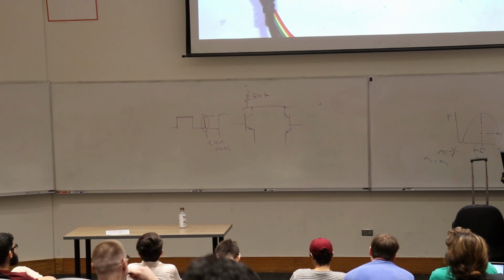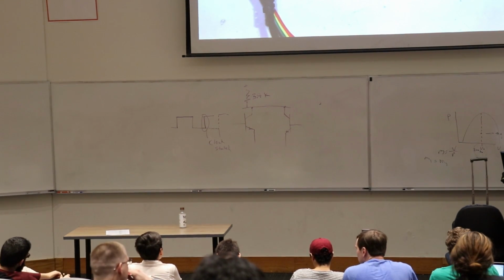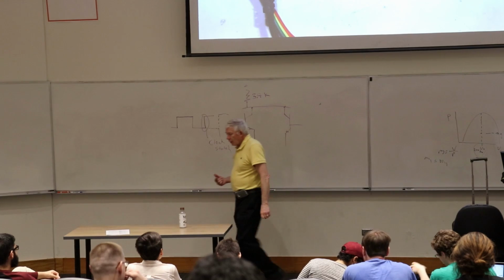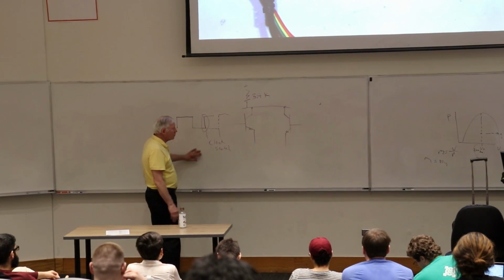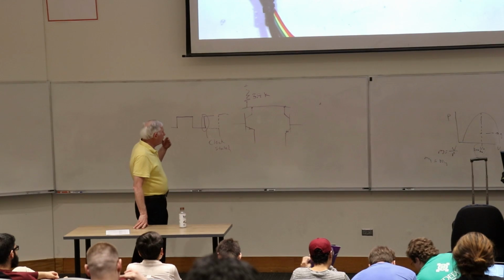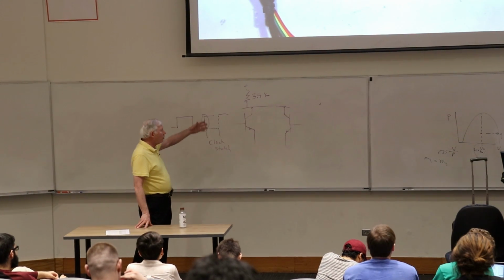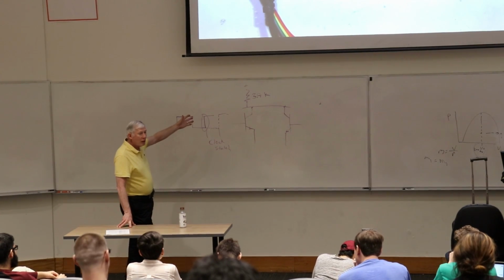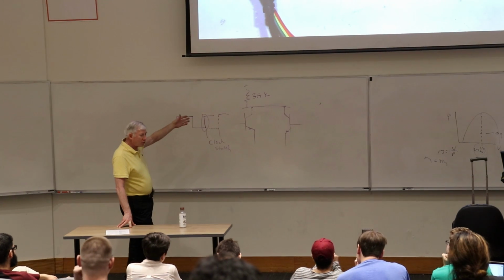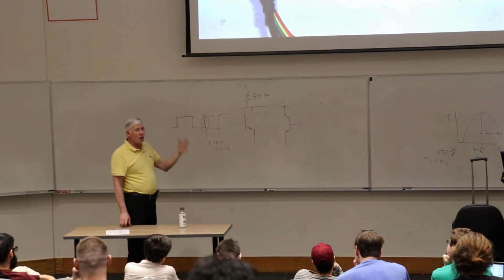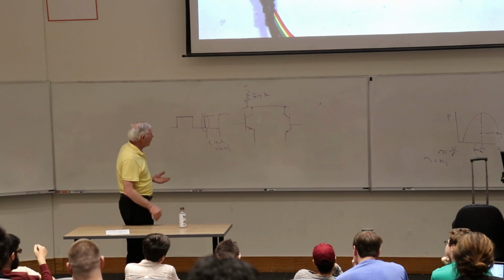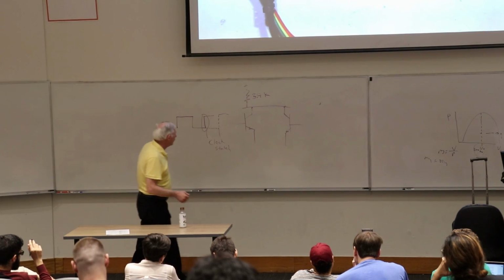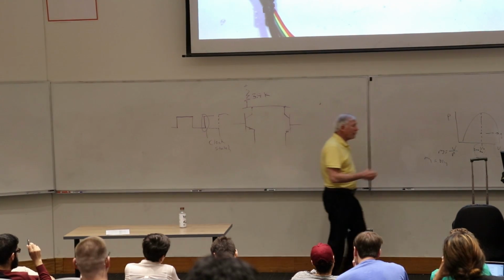It also can detect bus collision, and the whole idea of bus collision is very similar to what I just described, primarily on the data line. Normally when a master starts transmitting, it looks at the lines and knows if everything's idle, because both lines will be high. If it detects both lines are high and it waits for a small amount of time, then it initiates a start signal. The start signal is taking the data line low when the clock line's high. Normally you only do that when the clock line's low. And when that happens, it starts transmitting.